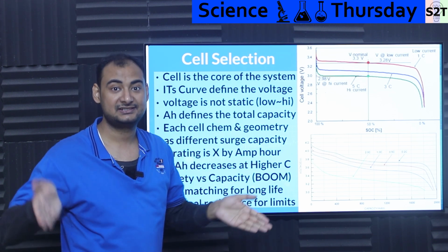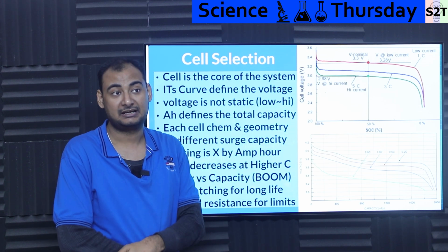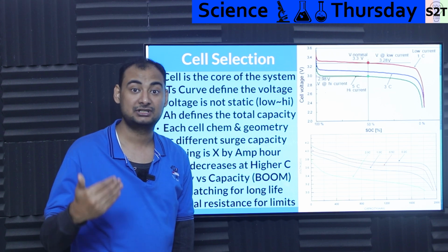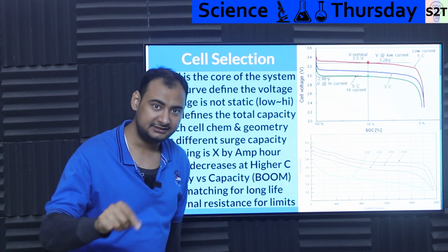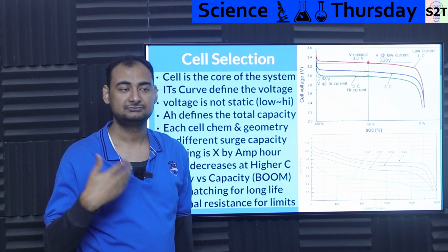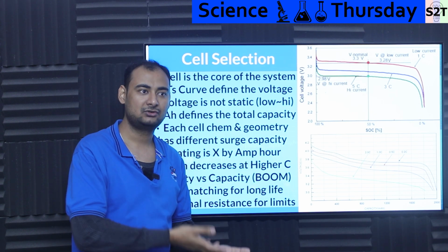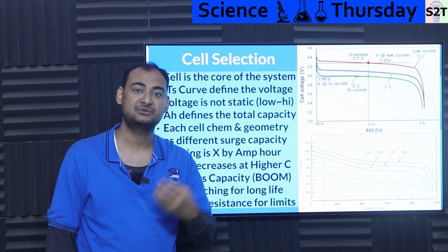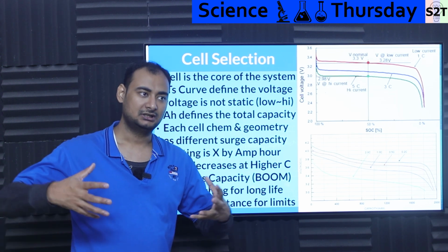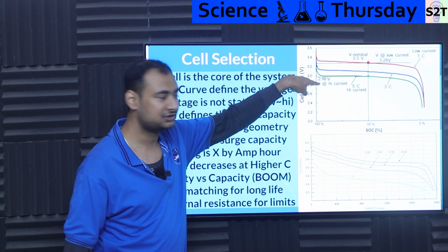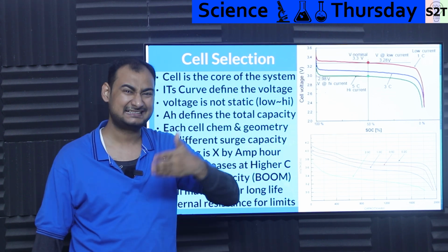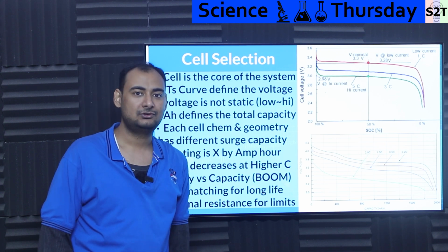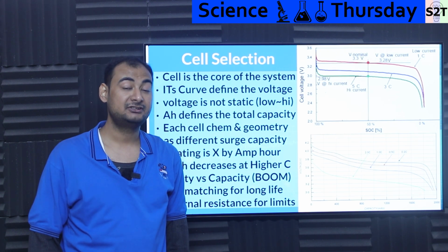For example, how many cells you have. You may say, hey, 2.98, I do not have enough cells. Okay, increase the number of cells so you have the exact voltage under load. Let that be very clear. Under load, you do not want to create an undervolt scenario. I put a load, and the voltage dropped too much. For example, in power delivery, you may require 20 volt at 5 amps for 100 watts, and because the voltage dropped so much and you had the cell count for 1C, that 20 volt is now dropped to 18 volt or maybe even 15 volt.